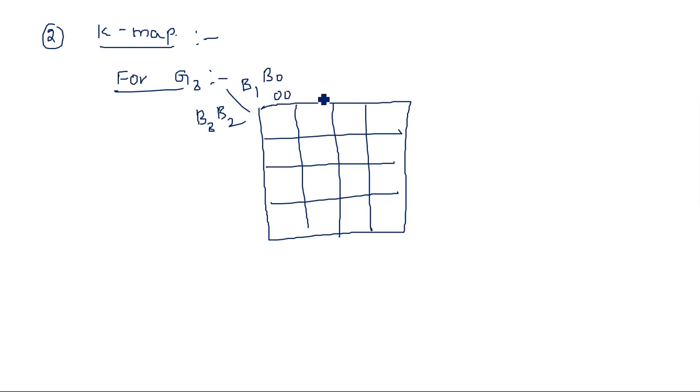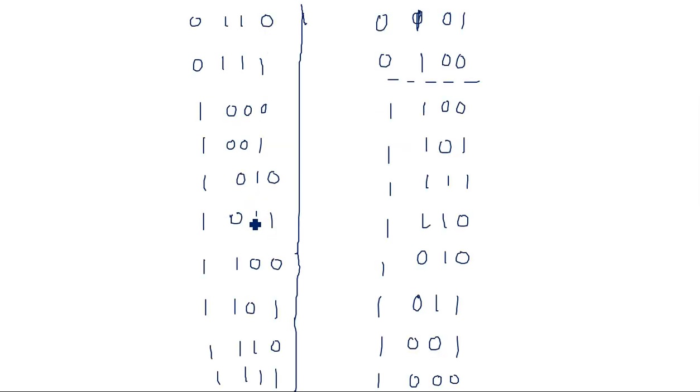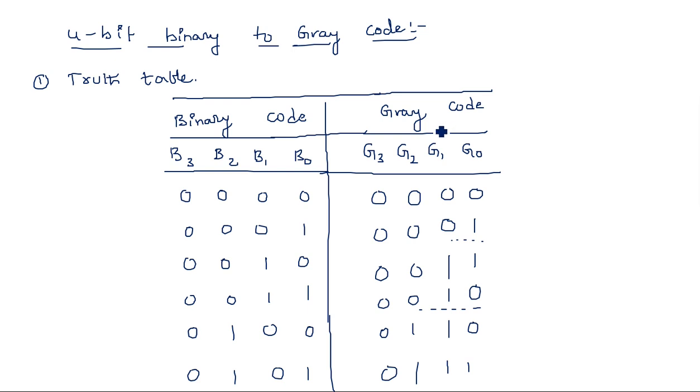So it is the gray code representation 00 01 11 10, and 00 01 11 10. Okay, your gray code is also known as unit distance code. Check whether you have unit distance between two successive codes. If you take the first and second numbers, it is 0001, so only one bit is varying from first to second.